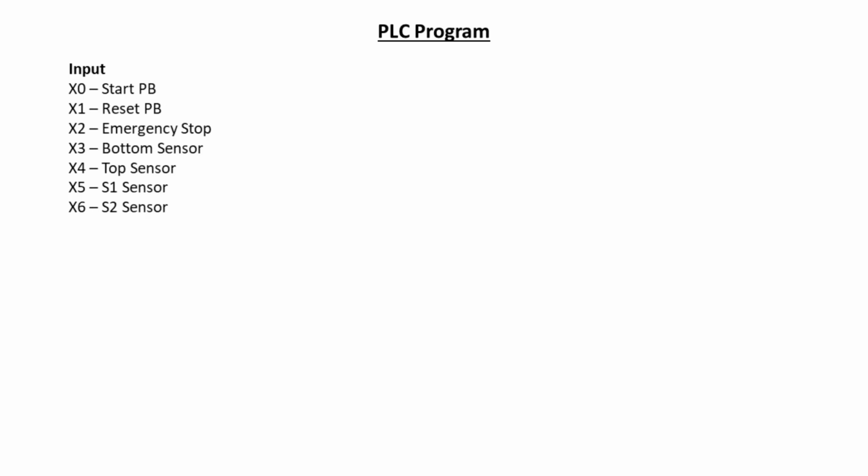We've linked the Start push button to the X0 input pin of the PLC, the Reset push button to X1, the emergency switch to X2, the bottom sensor to X3, the top sensor to X4, the S1 sensor to X5, and the S2 sensor to X6.